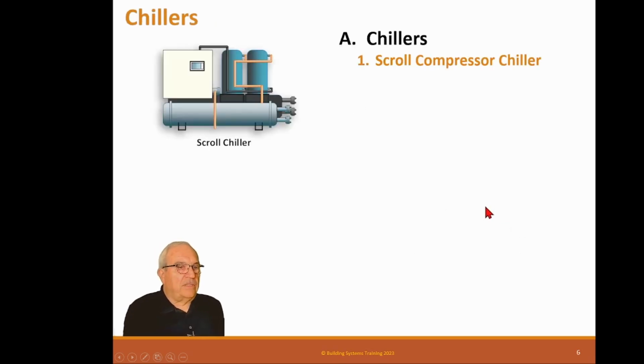There's all kinds of different kinds of chillers, and I'll try to go through and explain why they select the different kinds of chillers. This is a scroll or reciprocating compressor chiller, and these are small chillers, so we can get these clear down to 5 tons. So this would normally be a 20-ton chiller, or a 40-ton or 50-ton chiller would be in this kind of range. Small capacity, multiple compressors. So you have multiple compressors on here. So there's stages. So we got 2 stages.